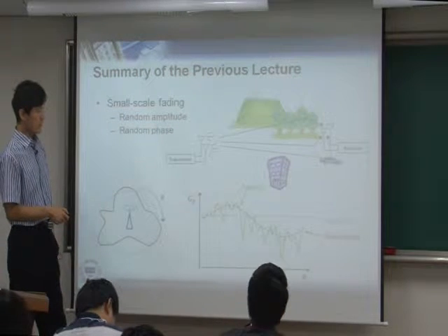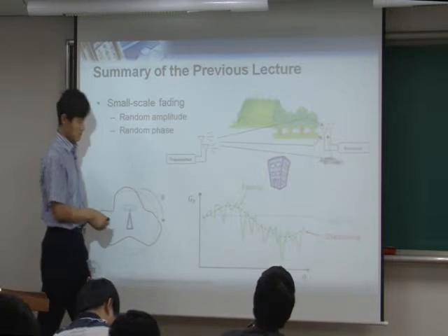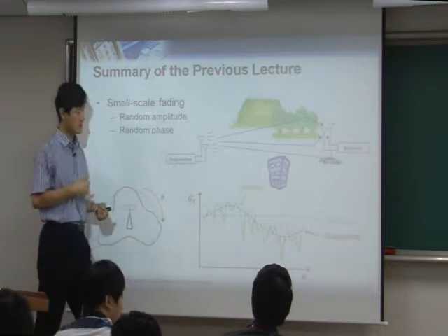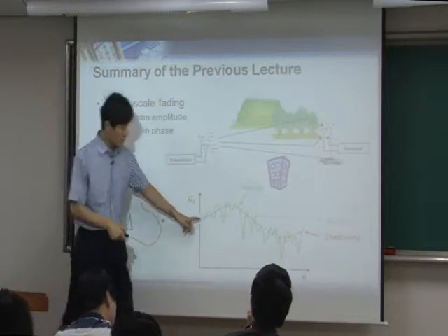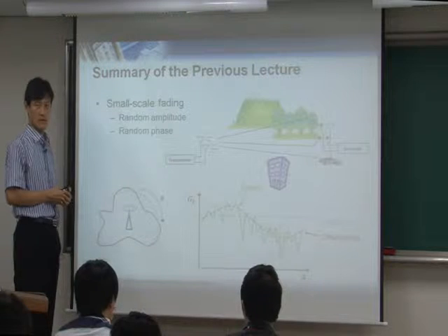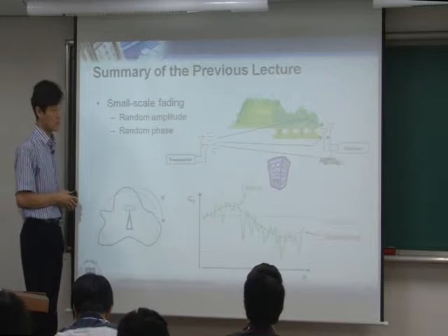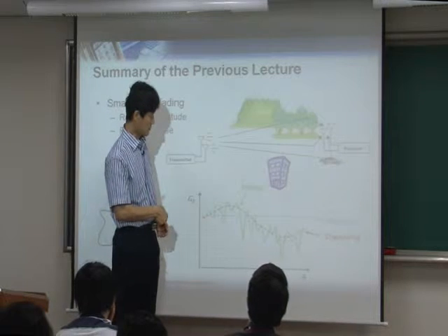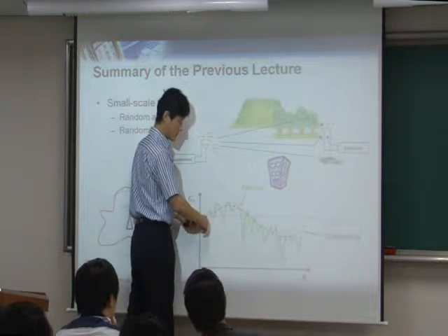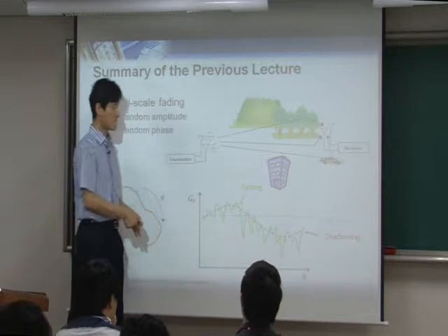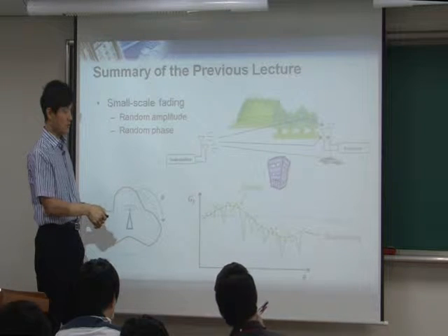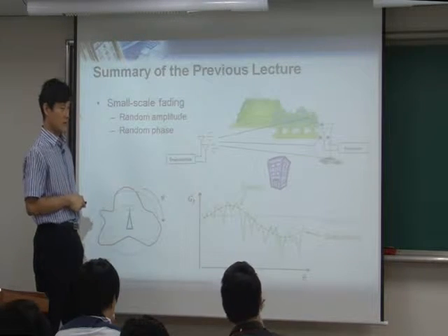Now let's think about small scale fading. Small scale fading is fading that happens very fast. Sometimes we call it fast fading. So this green curve is what you actually see in your receiver. We call it small scale fading because this fading happens on a very small scale over time and over angle, right? And this shadowing is middle scale because of this. This picture basically shows you why we call this one middle scale and this one small scale.